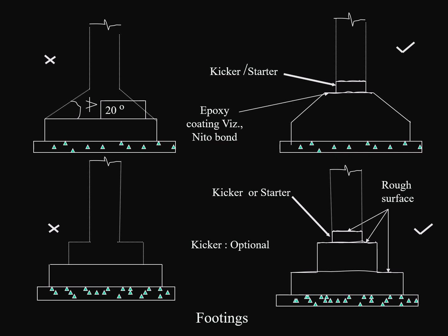In case of footings, whether it is stepped or sloped, provide kicker or starter to provide formwork properly, and the surface of the kicker should be made rough, whether it is stepped or flat footing or sloped footing.